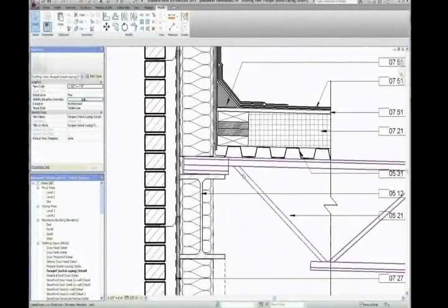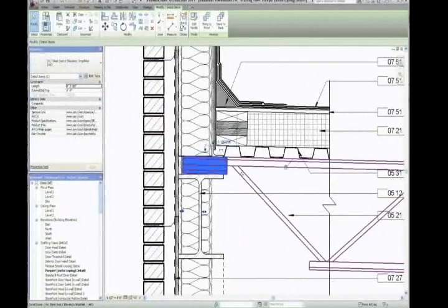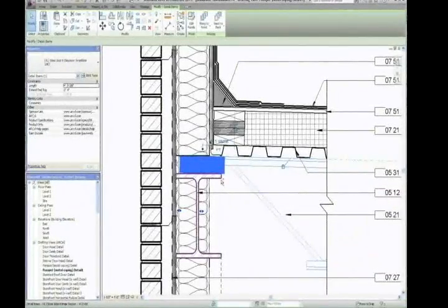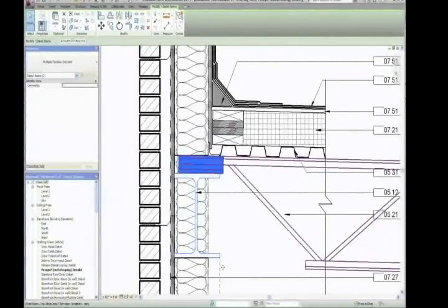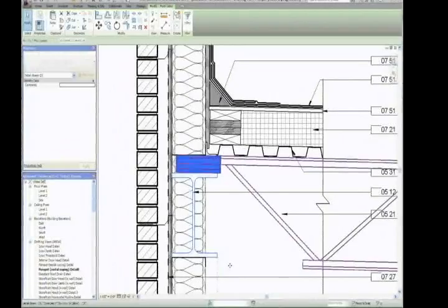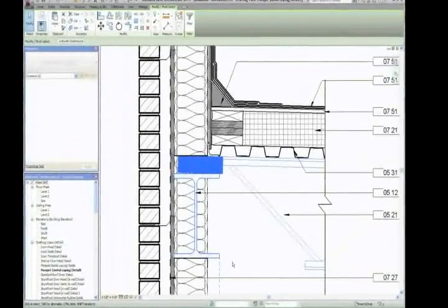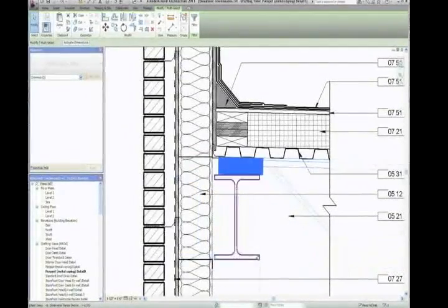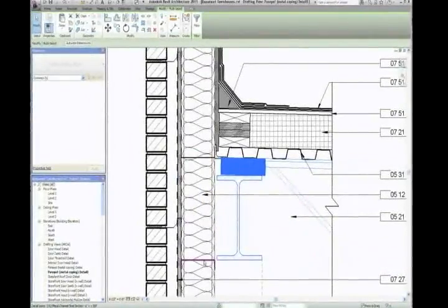Many details include studs running through the frame structure, so we'll correct that by selecting the bar joist, steel beam, and column line beyond all at once. You can use the Move command or right arrow key to relocate these into their correct positions. There are two stud tracks no longer needed that I'm deleting.